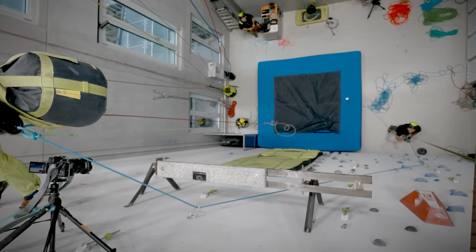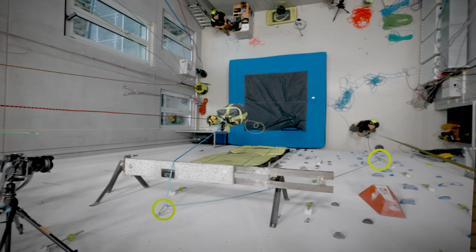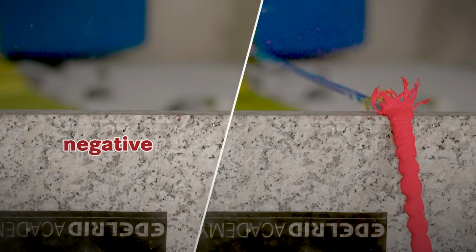And to fully concentrate on the different rope models first, Tommy, who was personally appointed as the belayer, was supposed to belay as passively as possible. So no active movement, just being a counterweight to the falling mass. So the rope we want to test runs through one quick draw before it is redirected roughly 30 centimeters above the edge. In this configuration, when the weight is dropped, the rope will hit the edge at about a 120 degree angle. The test is of course a binary one in general, meaning either the rope fails or survives.